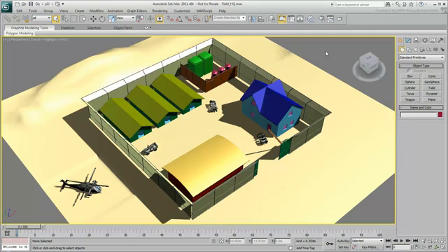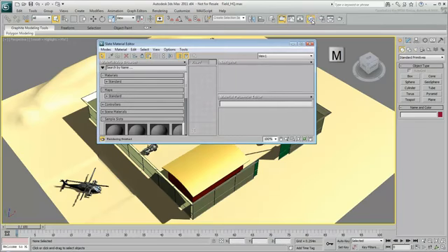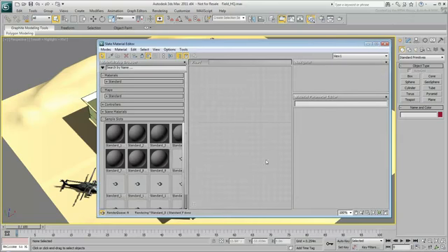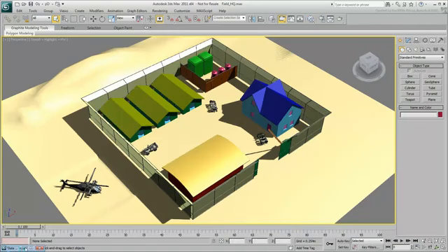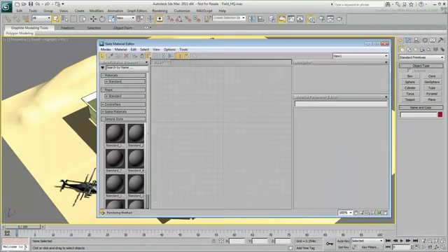In 3ds Max, you use materials to simulate effects including color, reflectivity, transparency, detail, and so on. You can create materials in the Slate Material Editor, which you can open by clicking the button in the toolbar or by pressing M on the keyboard. If necessary, you can resize the Slate Material Editor to see all 3 columns. You can also minimize it while you work to see changes in the viewport, then restore it when you need it again. You choose material and map types or ready-made materials from the Material Map Browser panel.